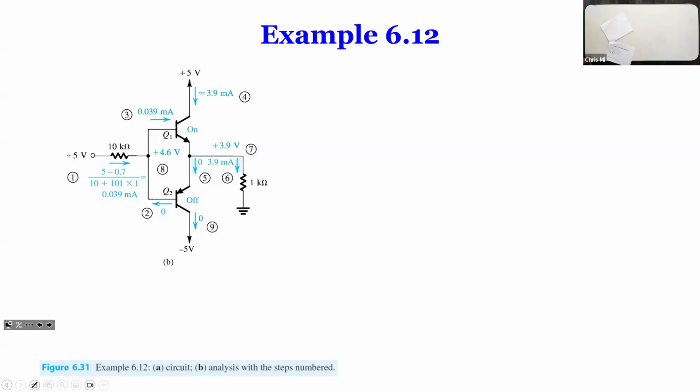Yeah, if it's in the middle, it is possible that both will be off instead. That's where, in a class B amplifier, you get what is called crossover distortion between +0.7 and -0.7. There's no output. The output is 0, because if it's 0, what happens?